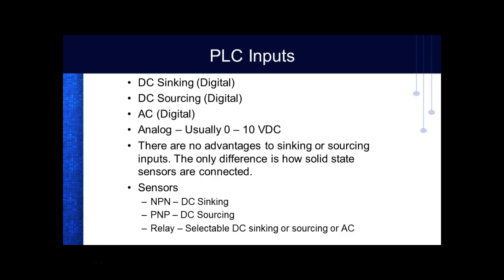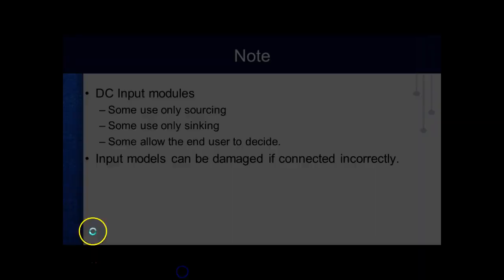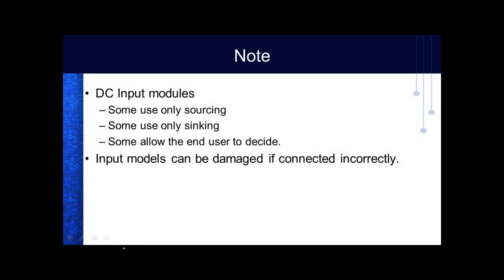You understand that? So what we do on AC is we decide one of our sides is going to be neutral. We call it a neutral. And then your neutral is going to be common to everything. And then what electricians call the hot lead, that would be the ungrounded lead. So what happens, I have a drawing set up on this thing.